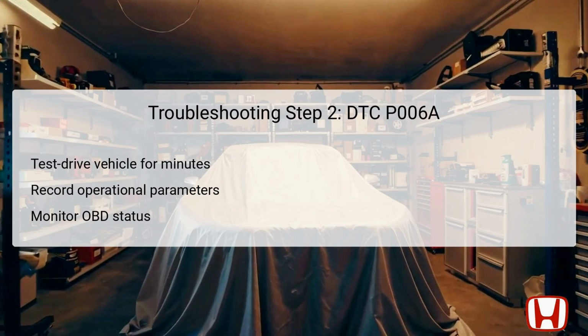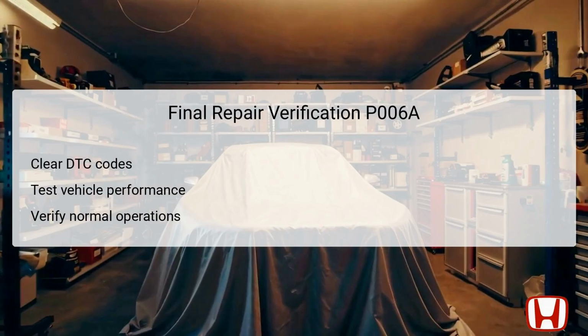The onboard diagnostics (OBD) status will then be checked using the Honda Diagnostics System (HDS) to determine if the P006A code persists, providing insights into whether the issue has been resolved or requires further investigation. After completing all troubleshooting steps and making any necessary repairs based on findings, the final step involves clearing any DTC codes stored in the PCM. This is typically accomplished using a diagnostic tool.